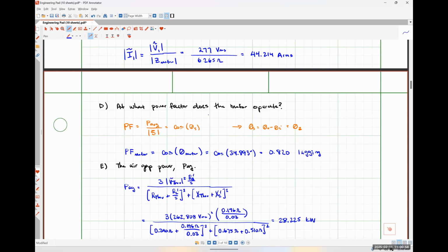So to me, if I rearrange that power factor relationship, it would be our apparent power multiplied by our power factor, where we know what our power factor is. Anybody remember what apparent power is? That is V times I conjugate, or the magnitude of V squared over Z conjugate.